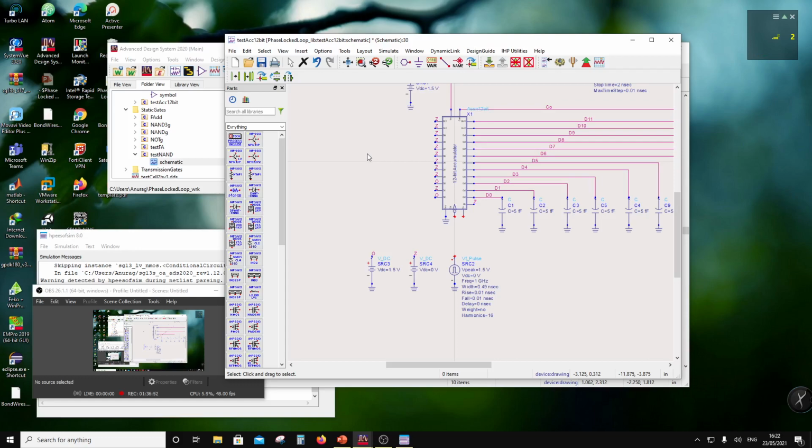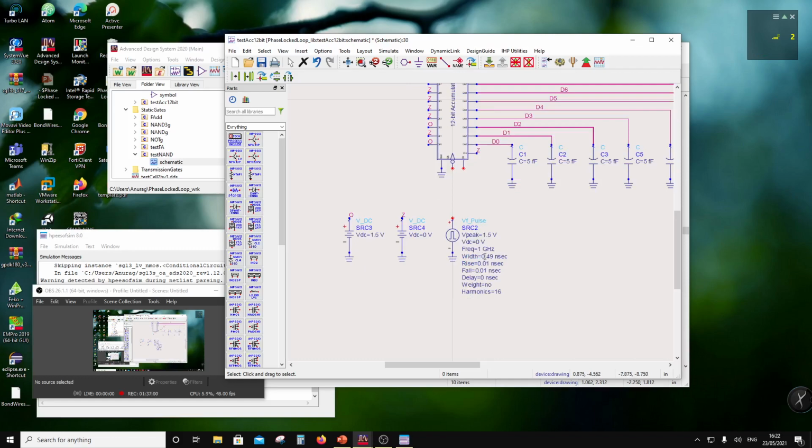So this is that, and I am going to put in a cycle which is going to be, so if this is going to be 100 megahertz, for example, then its time period is going to be 10 nanoseconds, right? And then the width is going to be 5 nanoseconds, right? So I would do a 499. So that's a 5 nanosecond. So that's driven at 100 megahertz.